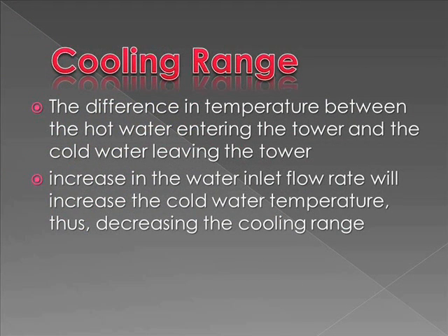The cooling range is the difference in temperature between the hot water entering the tower and the cold water leaving the tower. The trend here is that an increase in the water inlet flow rate will also increase the cold water temperature, thus decreasing the cooling range.